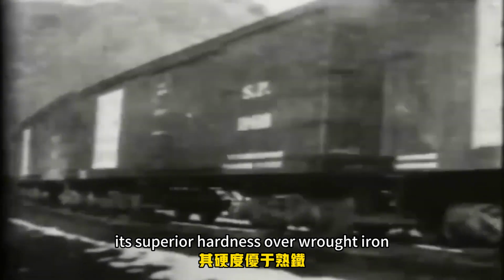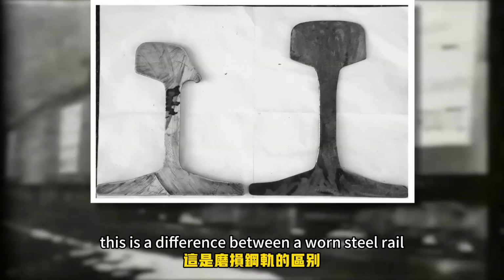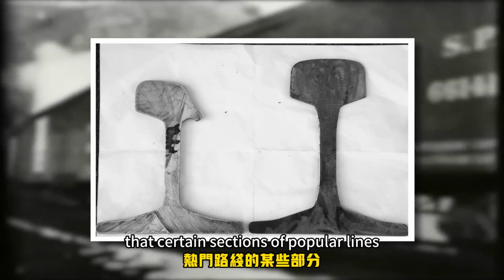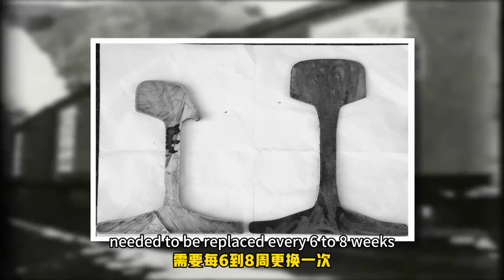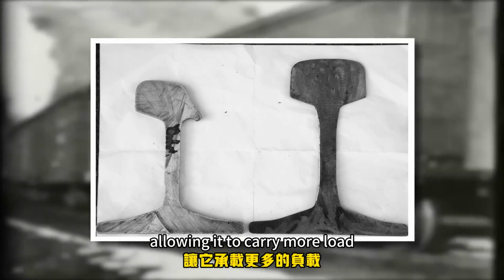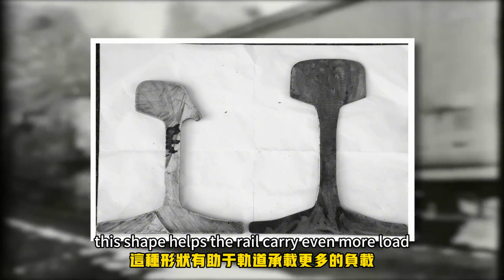Its superior hardness over wrought iron allows it to resist wear. This is a difference between a worn steel rail and a new one. This kind of wear happened so quickly with wrought iron that certain sections of popular lines needed to be replaced every 6 to 8 weeks. Steel also has a superior strength over wrought iron, allowing it to carry more load. If you watch my last video, you'll know why this shape helps the rail carry even more load.